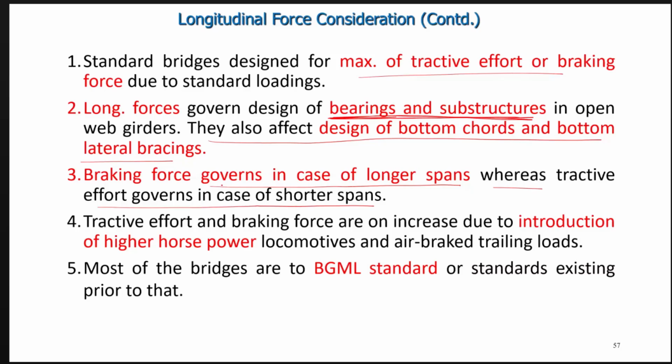Beyond that, there will be no tractive force, but braking force will be for everything including locomotive and wagons both. Tractive force and braking force are increasing due to the introduction of higher horsepower locomotives and air brake trailing load. Most of the bridges are BGML standard or standard existing prior to that.